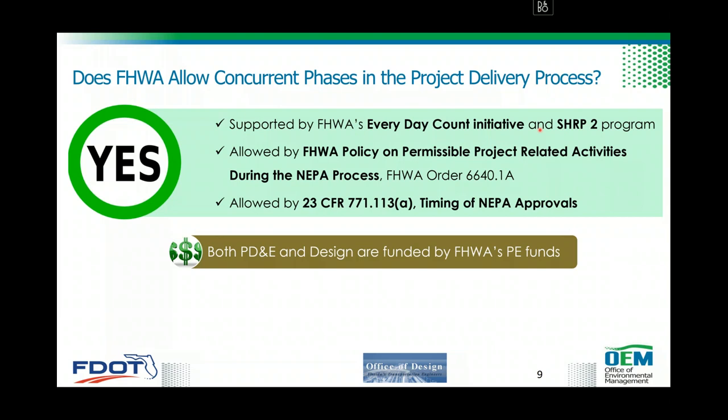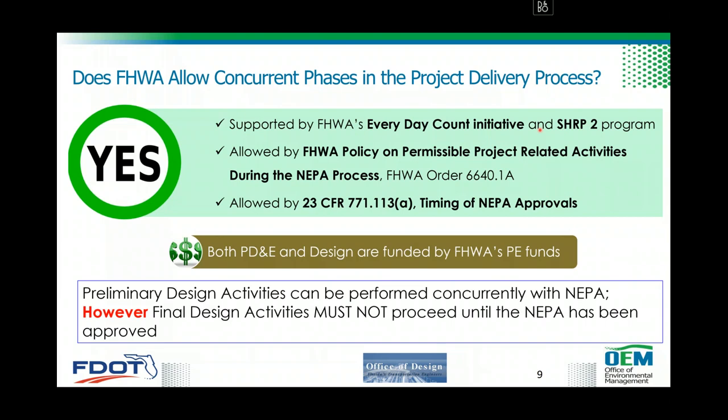In terms of funding, we don't have any problem there from our FHWA perspective, because both PD&E and design are funded by preliminary engineering funds. Preliminary design activities can be performed concurrent with NEPA. That's what FHWA says. However, final design activities must not proceed until NEPA has been approved.